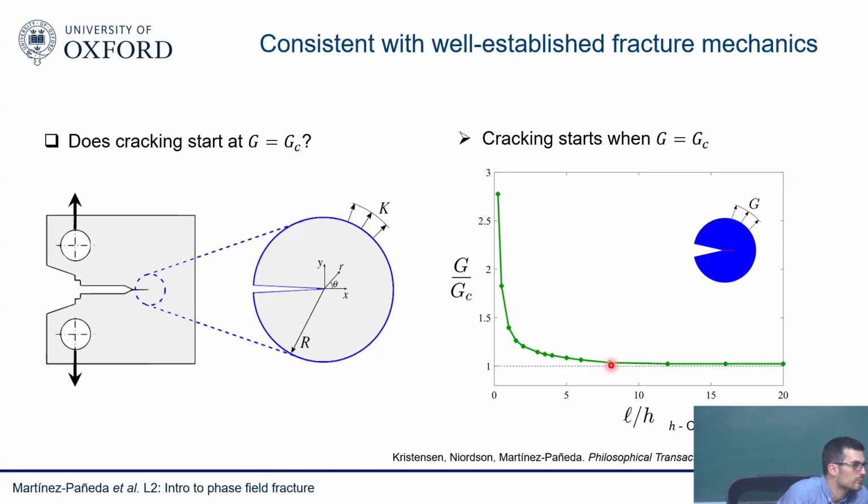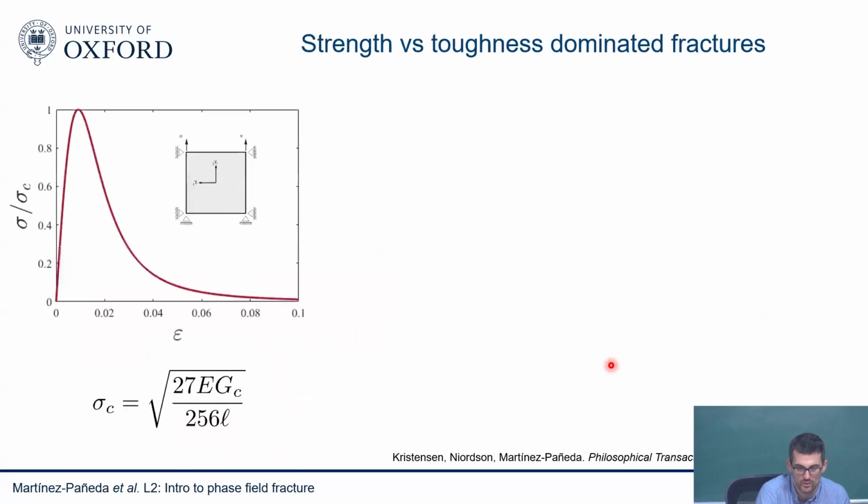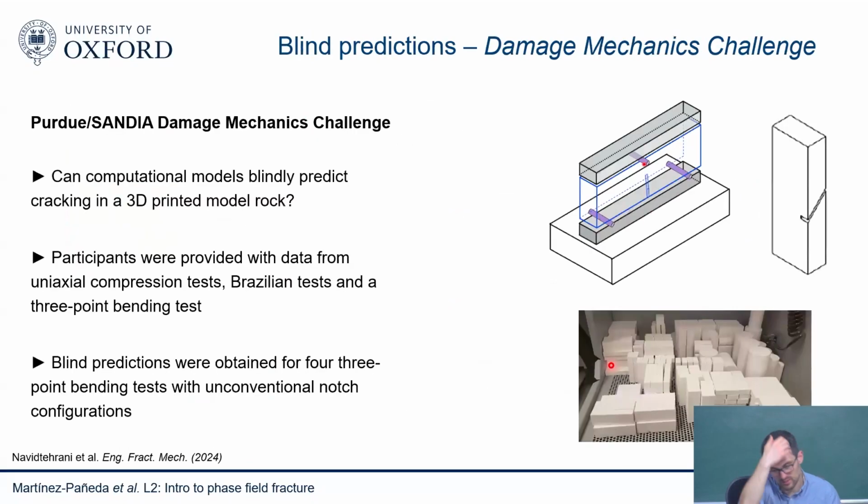Suppose for the same plate we are considering 3 dimensions, and we know it is uniform in the thickness direction. So in thickness, we can say we need a smaller number of elements compared to where the crack is propagating. Well, you do. If you have the crack propagating through the thickness, you need to resolve that. I'm going to show an example right now on 3D, so you'll see it. But you do need to resolve that.